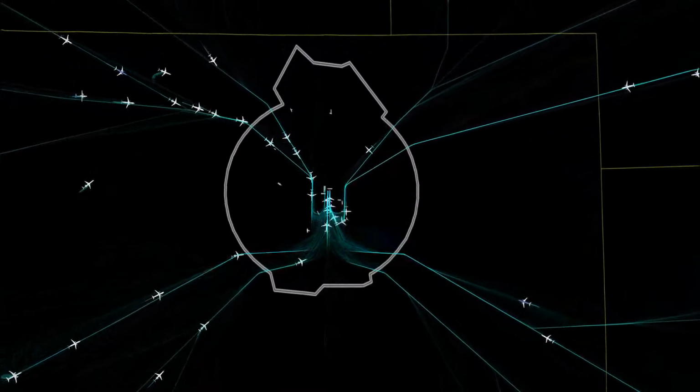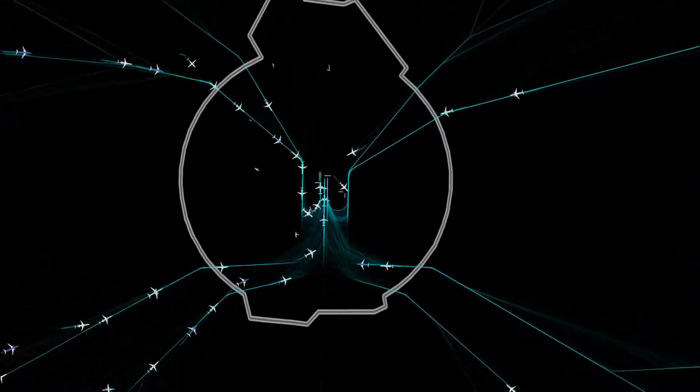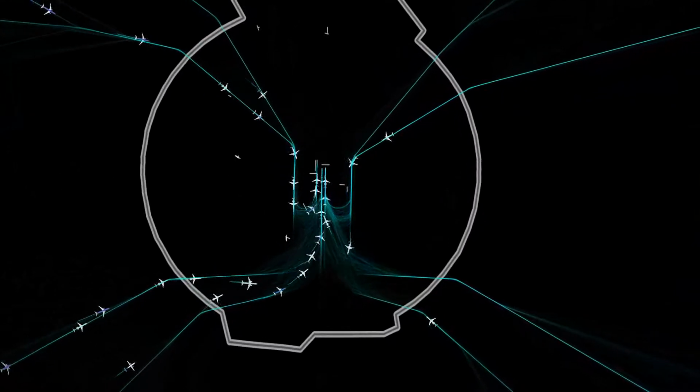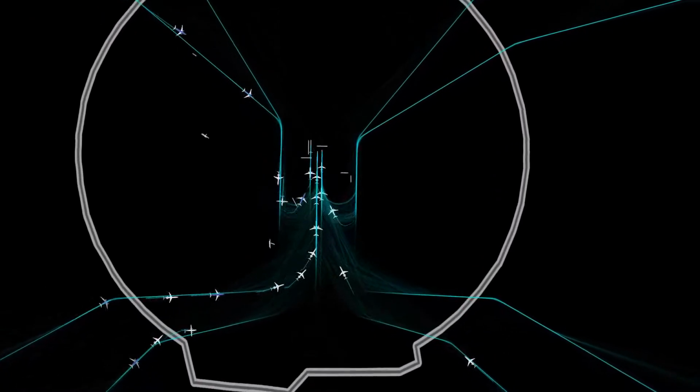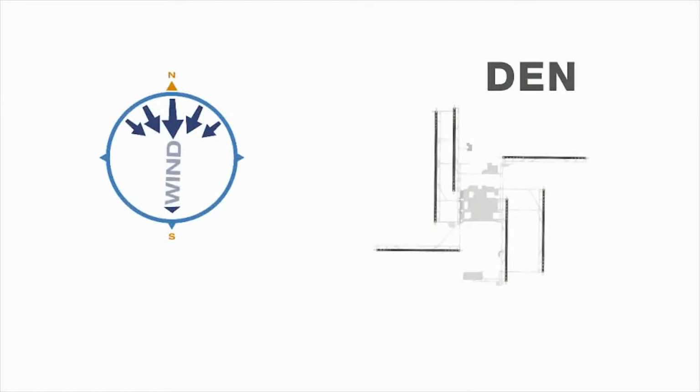In a busy airspace like Denver, a single controller is responsible for simultaneously directing aircraft for Denver International and multiple busy general aviation airports. Wind direction and velocity determine departure and landing direction. Aircraft generally must take off and land into the wind. Denver airports experience variable and strong winds, with the airport operating pattern changing to match the winds.